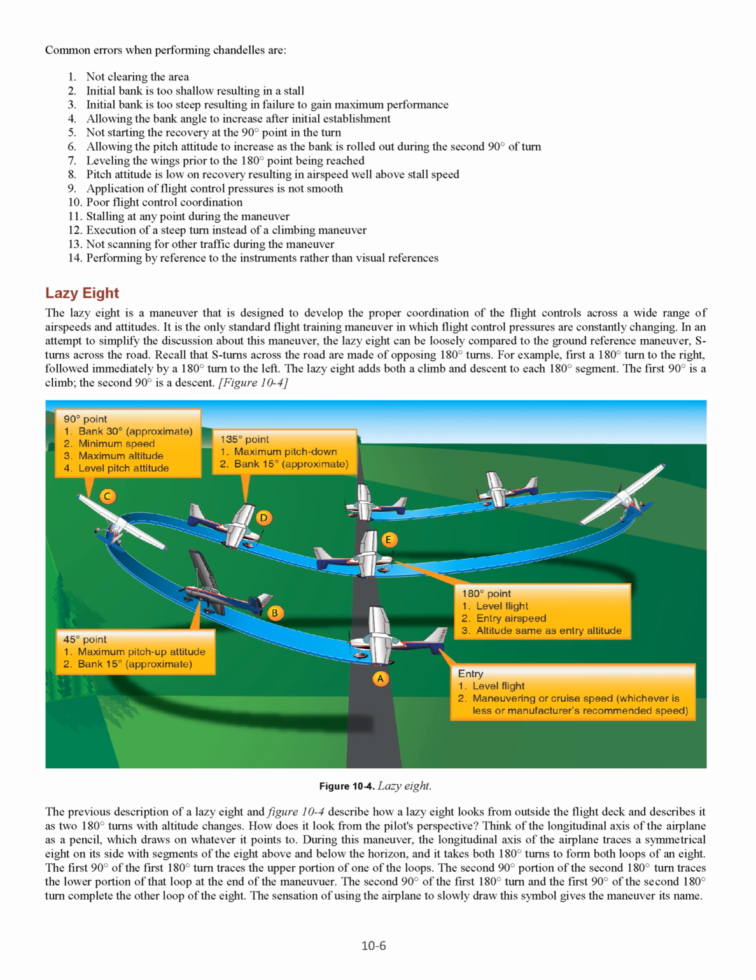Lazy 8. The Lazy 8 is a maneuver that is designed to develop the proper coordination of the flight controls across a wide range of airspeeds and attitudes. It is the only standard flight training maneuver in which flight control pressures are constantly changing.